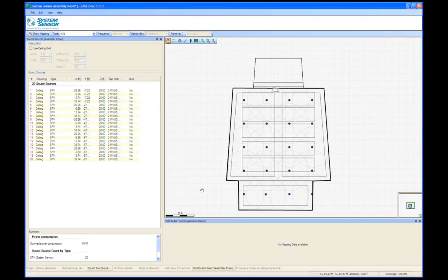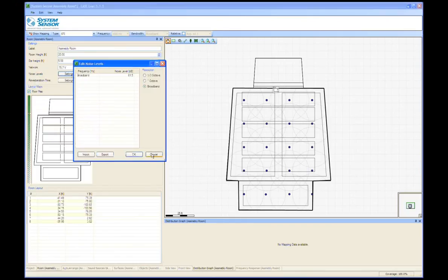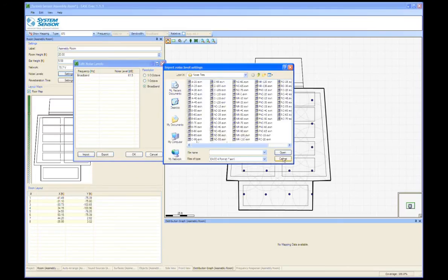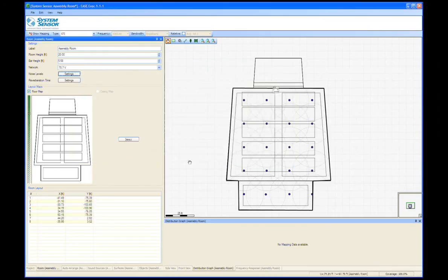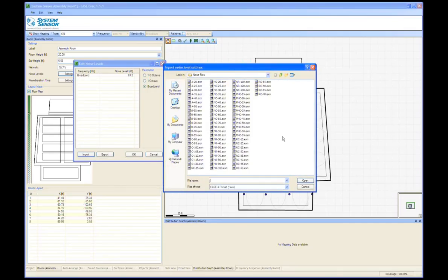Okay, very good. Next question is, what are the noise file formats? So what noise file formats and reverberation formats do you support within EASE Evac? I believe those are text file formats. Yes, they're both text file formats that are relatively straightforward. They have a specific extension, but you could open those in a text file editor to see the format and create those yourself. Okay. And a related question, where do you get these noise files from? Do they come preloaded, or is that from a secondary source? No, these noise files that I was showing to import actually come preloaded for EVAC. So you have all the different NC noise level curves, NR, PNC, and RC that you can select from. All of those are preloaded.